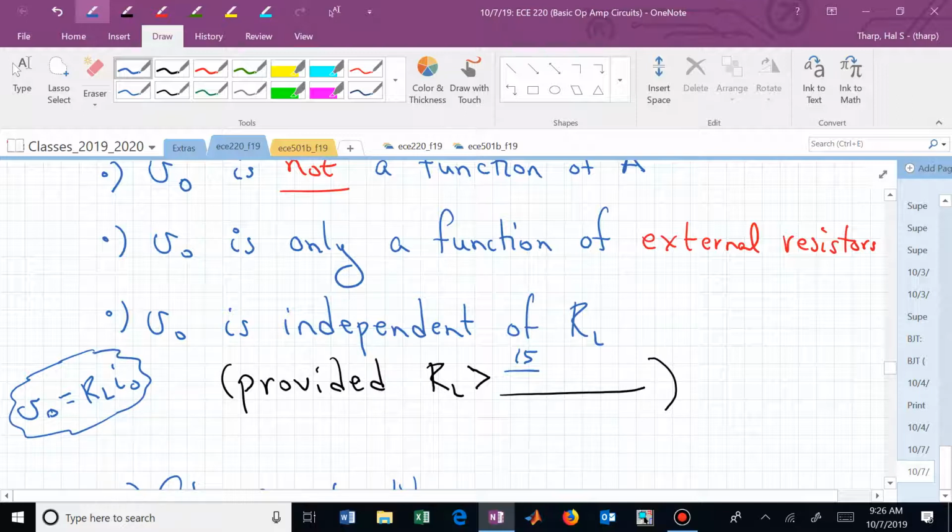If I solve that for R sub L, I have V sub 0, and V sub 0 can only be as big as a supply rail voltage, which is 15 in this case. And I sub 0 can only max out at 40 milliamps. If you do the numbers, this ends up being 15 divided by 4 over 100, or 1500 divided by 4, or 375 ohms.